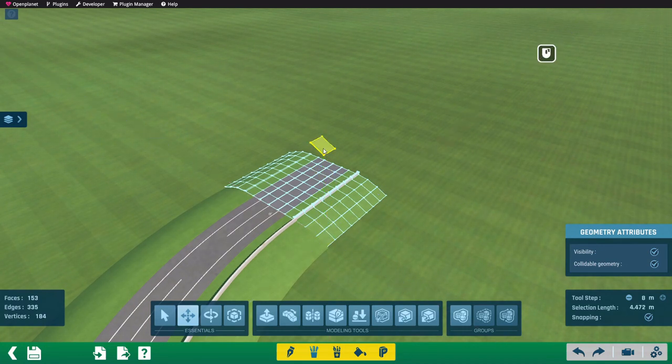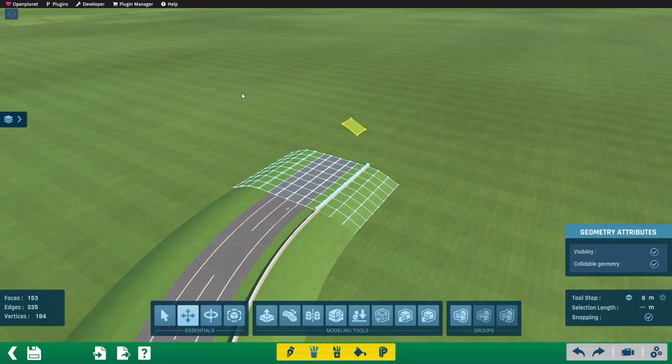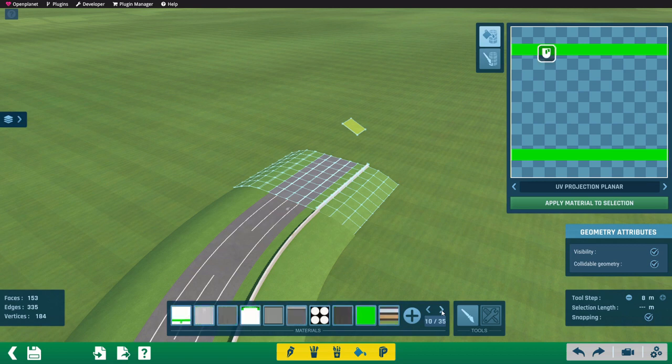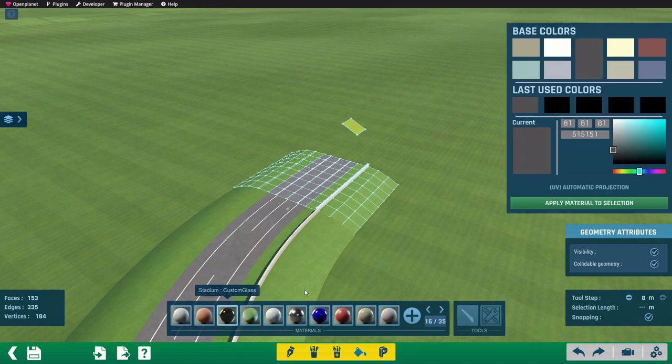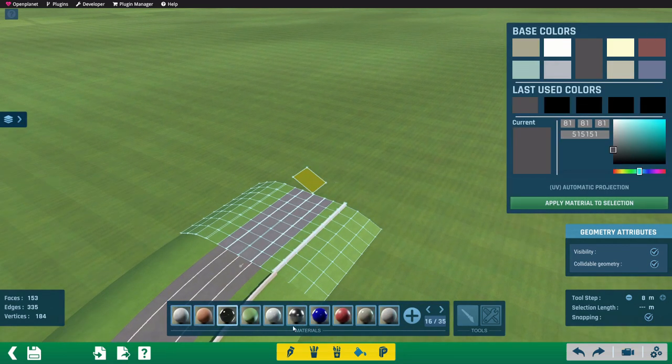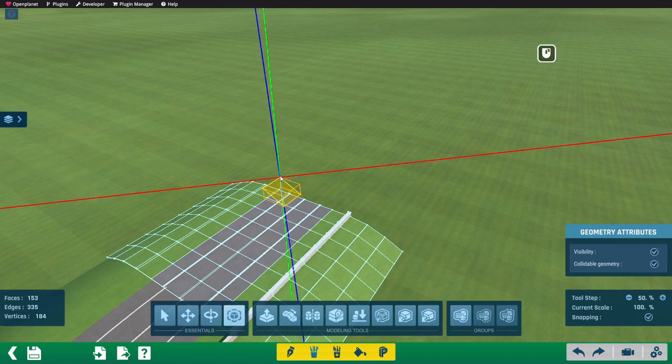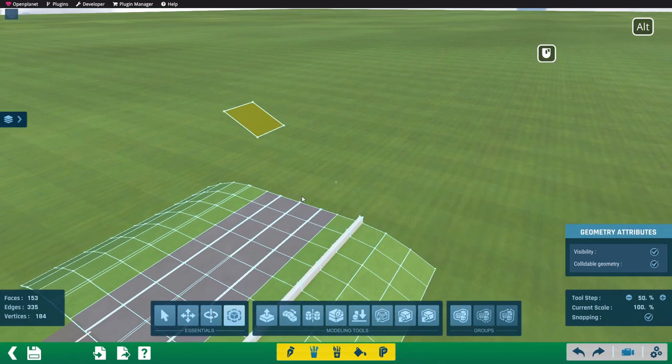However, we can manipulate this calculation without actually changing the effective racetrack geometry. Just copy a face beside the track in the yellow mode and place it way above the geometry. Scale it down to a very tiny size and use a surface without shadows like glass, or even better, an entirely uncollidable surface. Now the center of the banking rotation is above the track, which creates smoother banking transitions. But there is no right or wrong pivot point of the banking, it depends on your preferences.